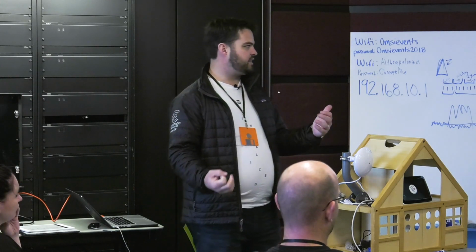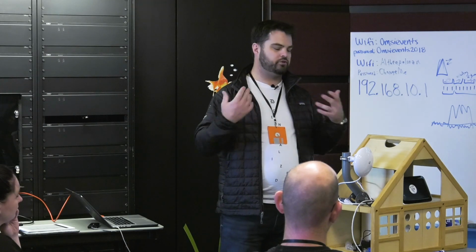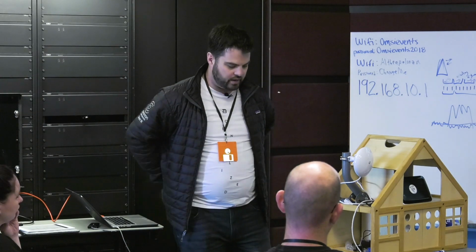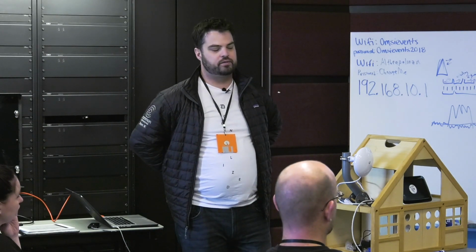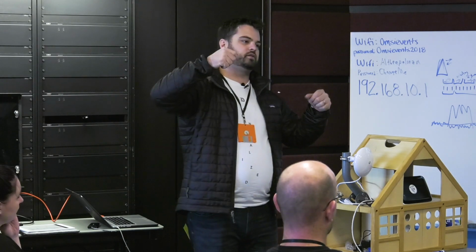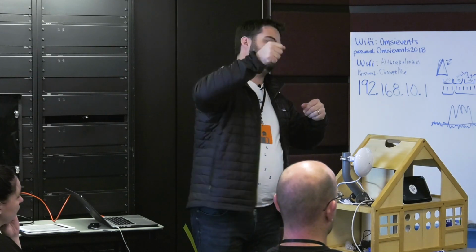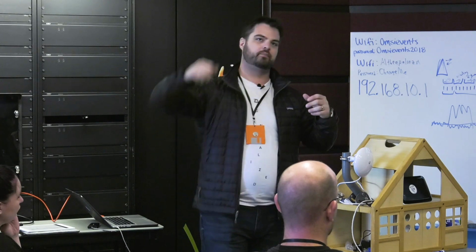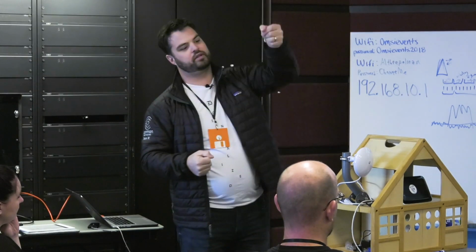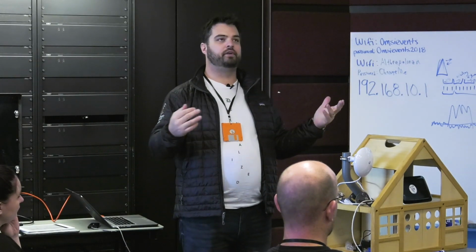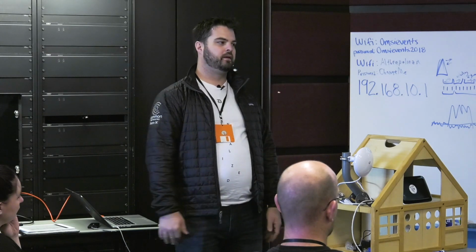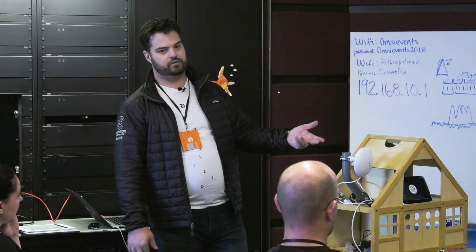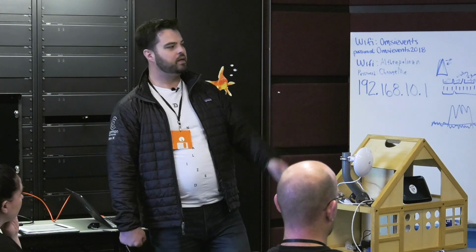Staying safe on a tower yourself is pretty straightforward. You put on a harness and then you have what we call Y lanyards. You've got basically 2 hooks and you never leave yourself unconnected. As you climb, you hook with one hand, then you climb and you hook with the other hand, so that at any point if you fell, those Y lanyards would catch you. That in itself is pretty simple and straightforward. You can do it with an hour of practice.